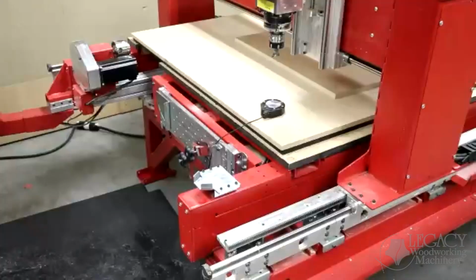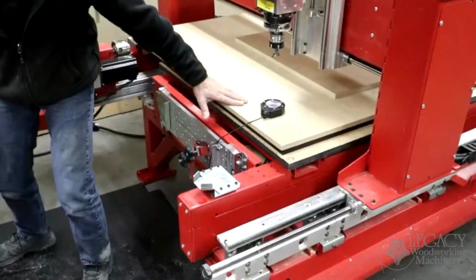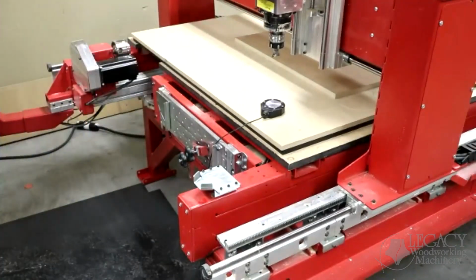That's the number one mistake I've seen with Smart Tool: somebody touches off single tool, then they enable the Smart Tool so that it touches off again and resets your Z, and that's not cutting the proper depth. Okay, so that's how they work. The second one, the single tool, when we touched off this one right here, it set the Z to the surface of material underneath right there, and then it just raised up.